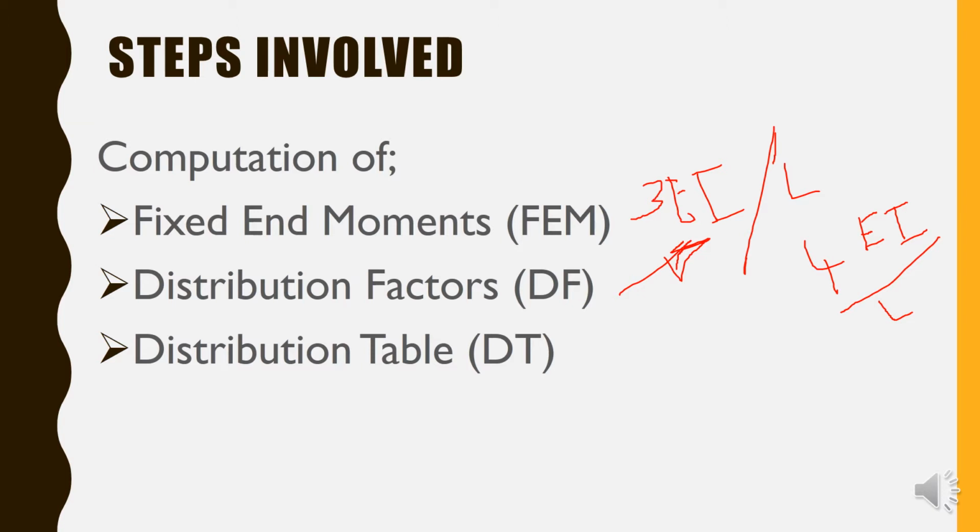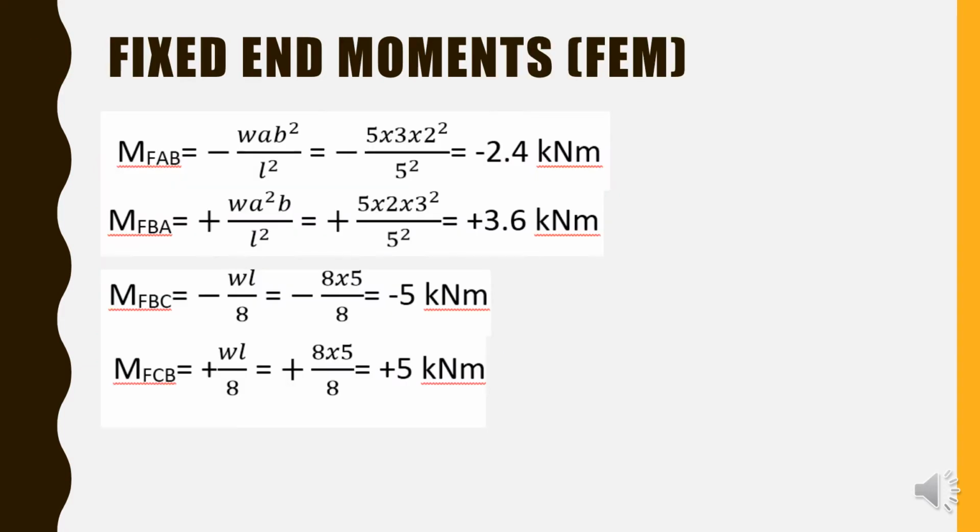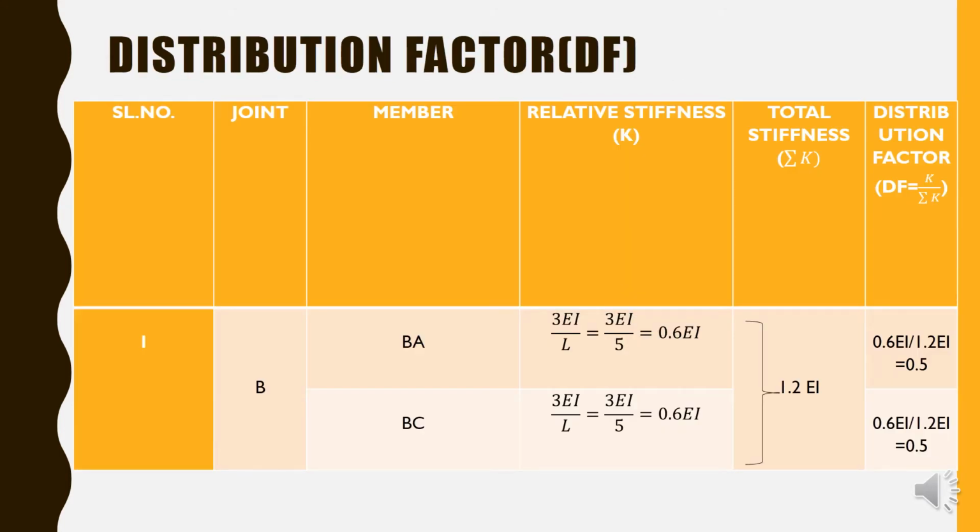For the fixed end moment, the common procedure is to use the fixed set of formulas, that is for UDL, for point load, for uniformly varying load. All those formulas that we have learned in slope deflection will be used to calculate the fixed end moments.